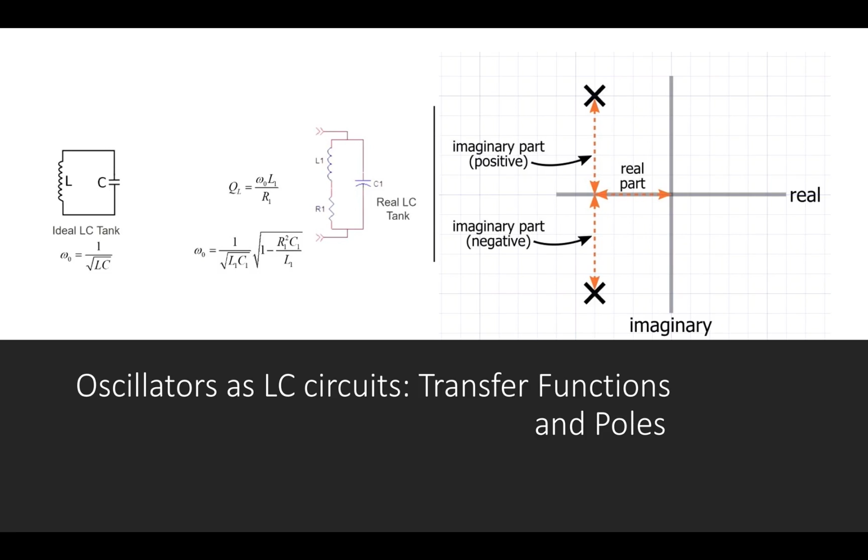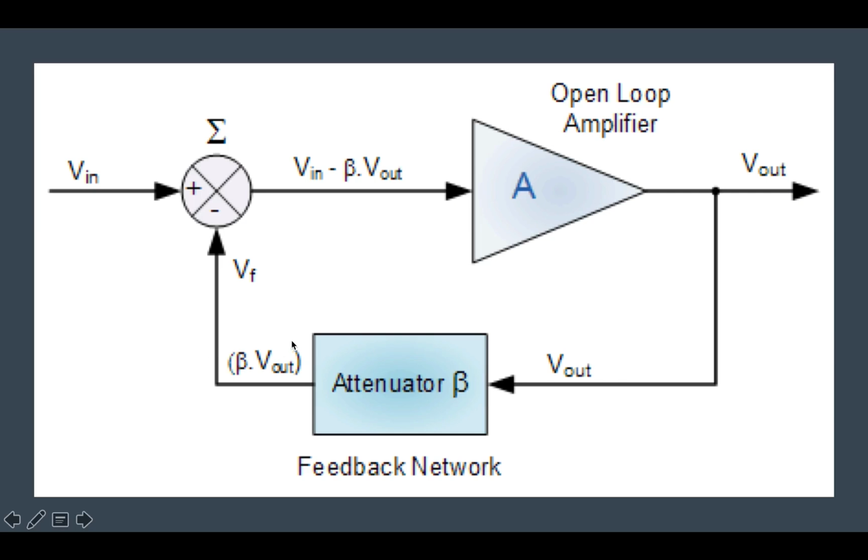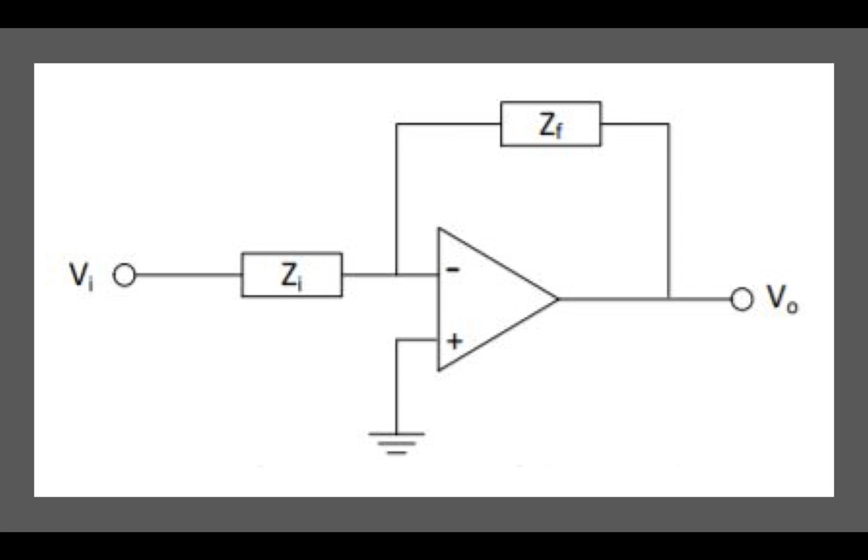They overcome losses of the feedback resonator circuit, which we can see here, the feedback network, and these overcome losses because of capacitors or inductors, as we can see here for these load inductances, into the resonator circuit. In other words, an oscillator is an amplifier which uses positive feedback that generates an output frequency without the use of an input signal.